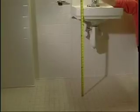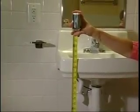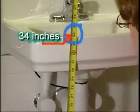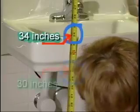For instance, when dealing with the height and knee clearance of the lavatory, you can take both of these measurements at the same time. Is the top of the rim of the lavatory no more than 34 inches above the floor? It's 34 inches. Okay, and is the bottom of the apron at least 29 inches above the floor? It's 30 inches.